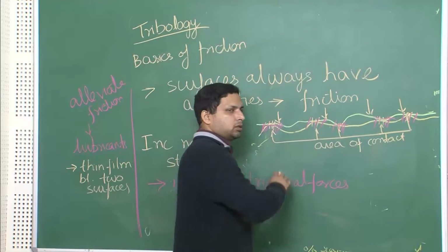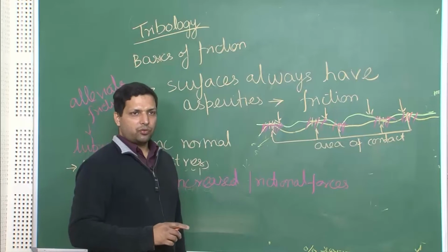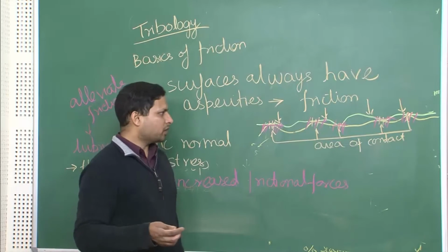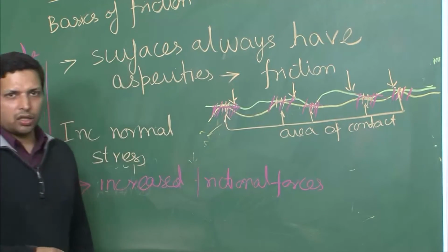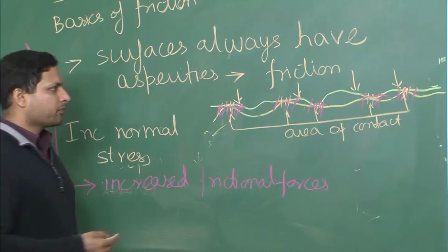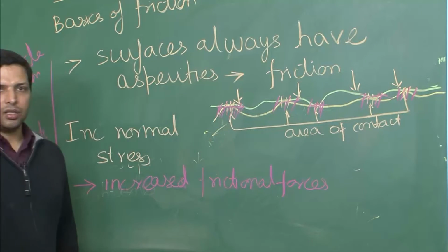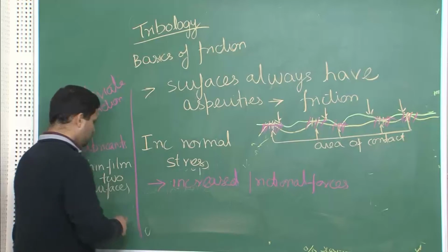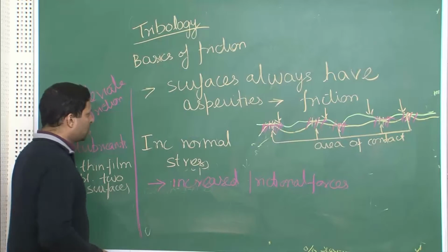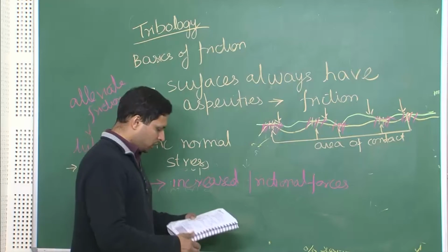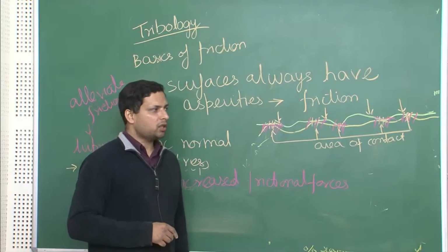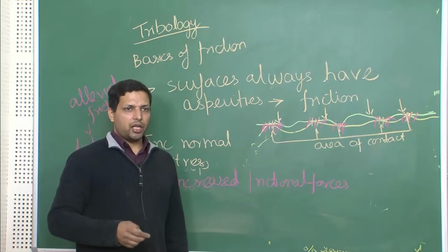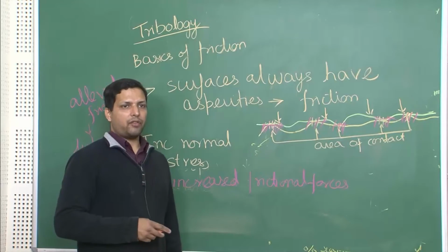Now, the shearing of liquid, we know, is very easy; it requires much lesser stresses, and therefore the surfaces can shear very easily against the liquid film, and they are not really shearing against each other, and hence we are able to reduce friction. So, that brings us to the important aspects of friction, particularly I should say the deleterious effects of friction.